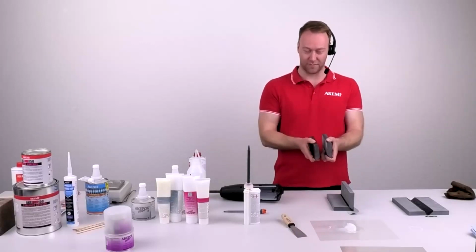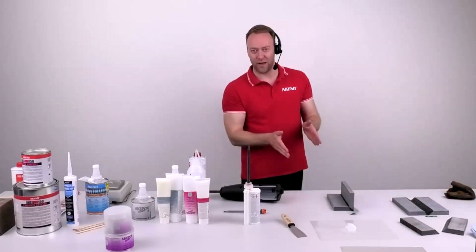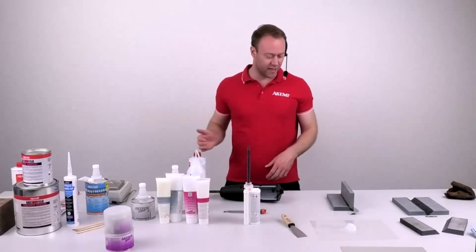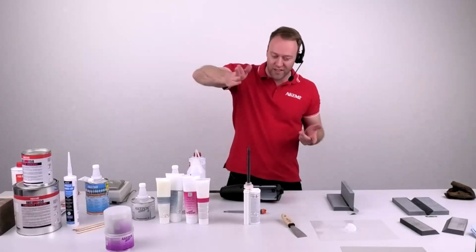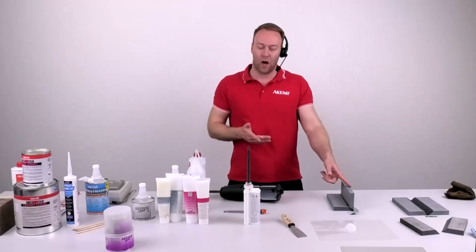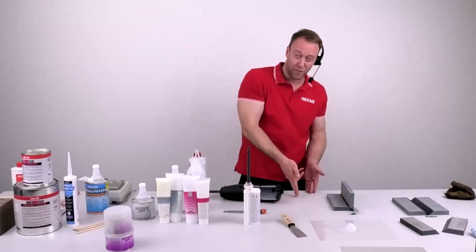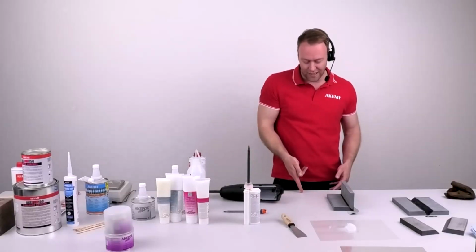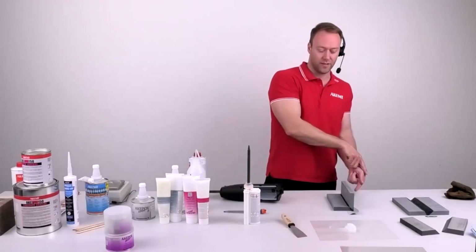Cover both sides. Of course, a special case is this miter bonding with the 45 degrees, because it's usually done online. They do a lot of running meters there in production. They want to work fast, so they don't go with the spatula and apply on one side and another side and then press together. They do what I've done. They go in the center, they press a lot of glue, they don't go zigzag. They put the glue inside so that when they press together, it comes out on the one side and on the other side.